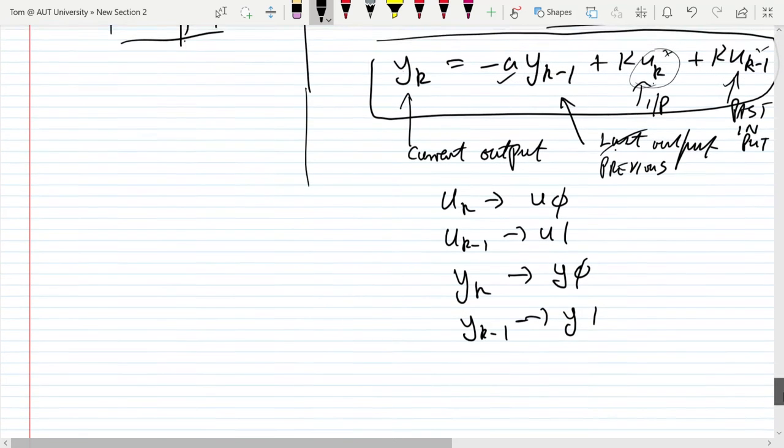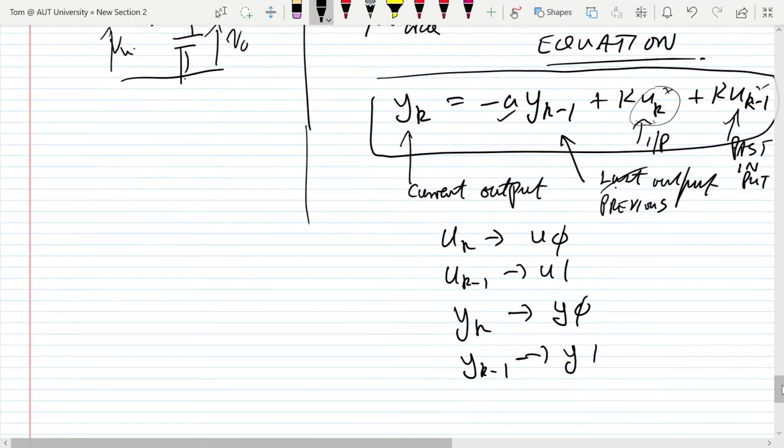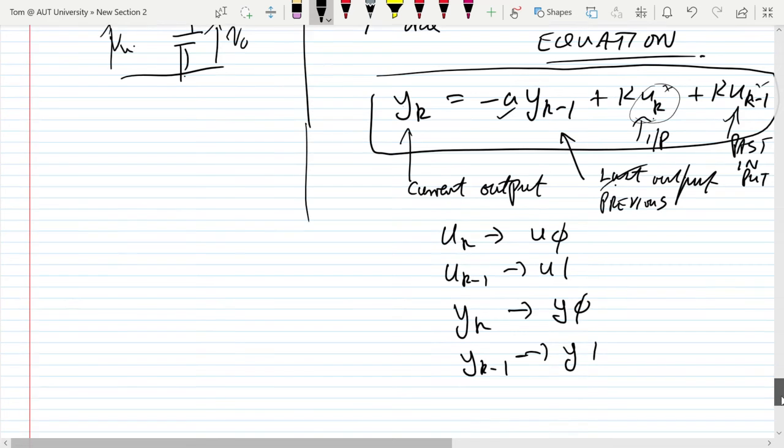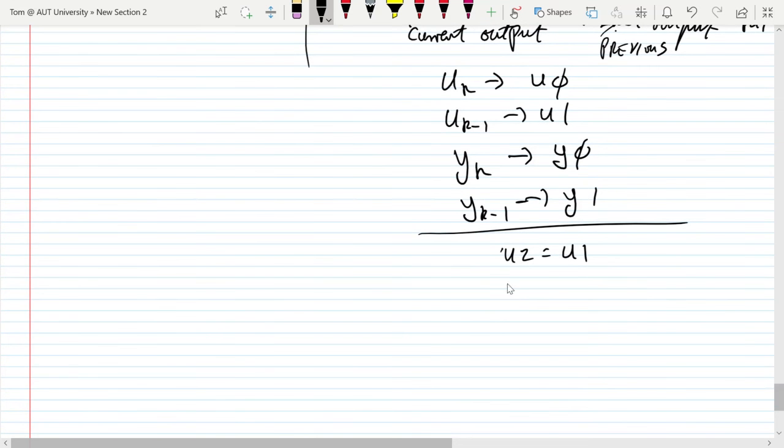Okay. So what I'm trying to implement is this guy up here, y of k is equal to a, y of k minus 1. So to implement in the software, all I need to do is say, well, u2 is equal to u1, and then u0 is equal to, and then I need to read the input from somewhere.